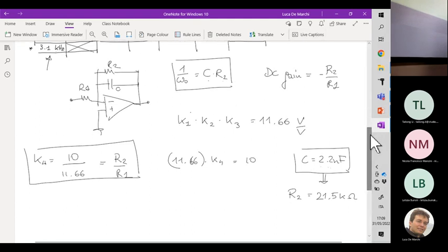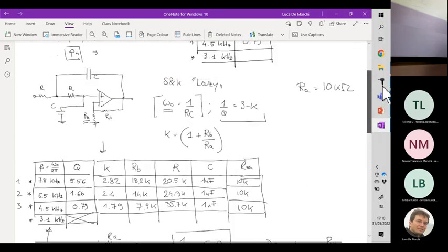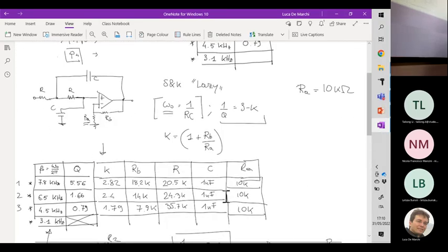So you have set R2, then you plug R2 here, and finally you define the value of R1, which imposes this relationship between R1 and R2. So in this specific case, you need an R1 which is equal to 24.9 kilo. So let's make a short break, and then we will design the whole topology. Basically, we have specified all the circuit parameters which are needed for the final design.